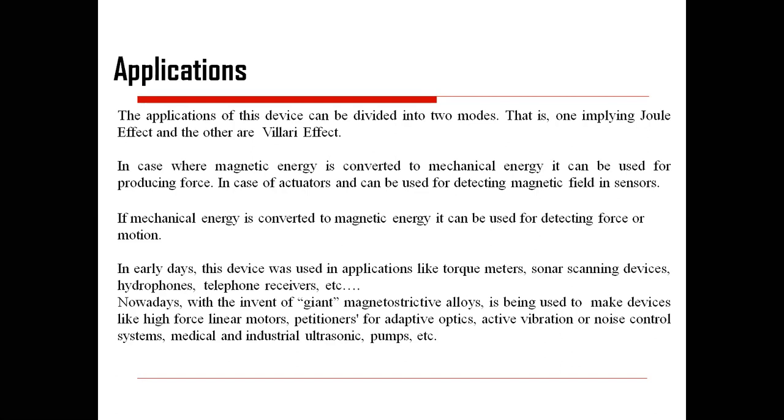So in recent days or previous days also, this device was used for a large number of applications: torque meters, sonar scanner devices, hydrophones, telephone receivers. And in recent days, with the advent of Galfenol, magnetostrictive alloy is being used to make devices like high force linear motors, positioners for adaptive optics, active vibration or noise control systems. Then there are medical applications, a large number of them.